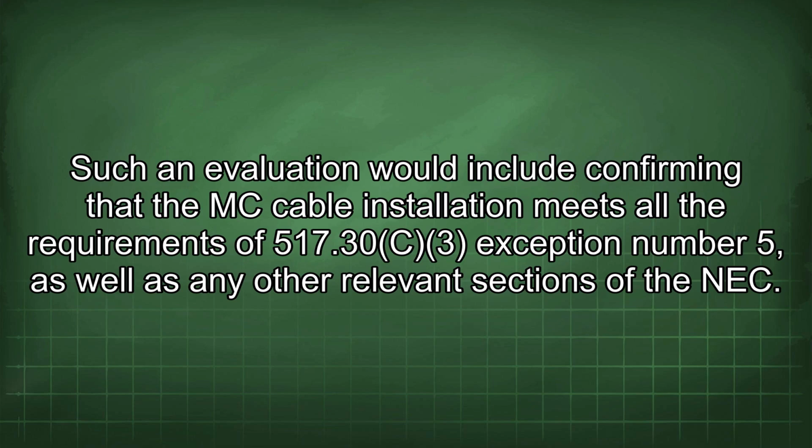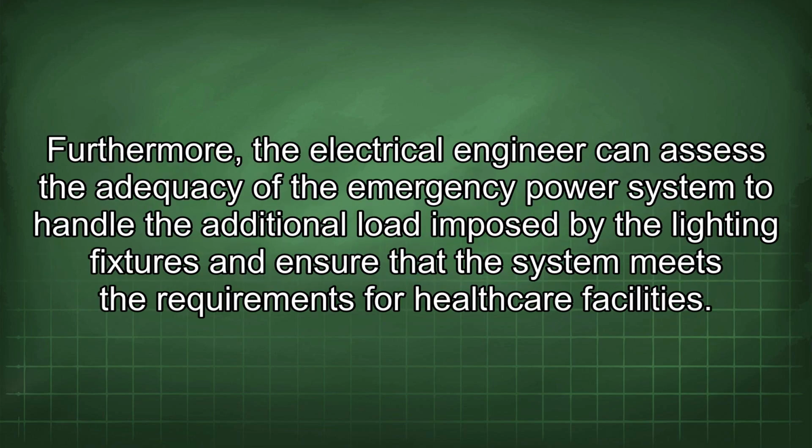Such an evaluation would include confirming that the MC cable installation meets all the requirements of 517.30 C3 exception number 5, as well as any other relevant sections of the NEC. Furthermore, the electrical engineer can assess the adequacy of the emergency power system to handle the additional load imposed by the lighting fixtures and ensure that the system meets the requirements for healthcare facilities.